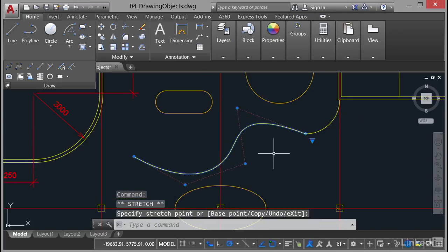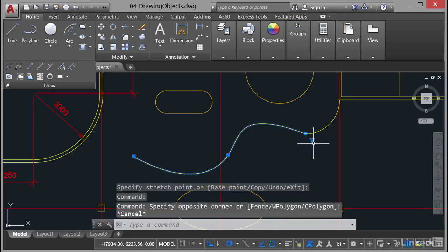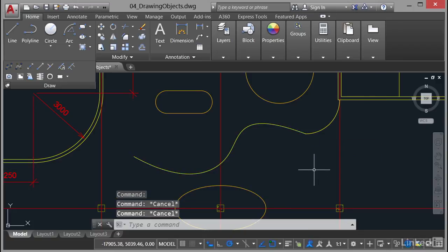It's a really, really nice tool for creating gentle curves that you might want to work in. It's also parametric. It's dynamic, so I can click there. I can either change it from a fit like that, and there's my fit points, or I can change it back to my control vertices just by clicking on that triangle there. So if I change that back to control vertices, they're back like so. I just hit escape to deselect. So that's how you create a polyline and a spline when you're working in AutoCAD. And they can have many, many different uses as well. So just be aware of that, and you can work with those and develop some really quite clever and neat designs using polylines and splines.